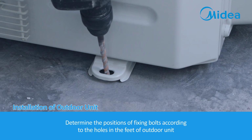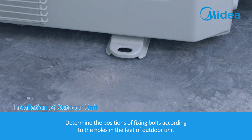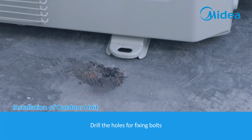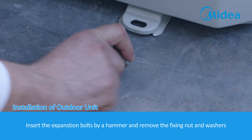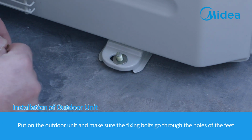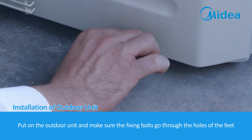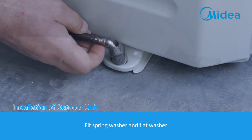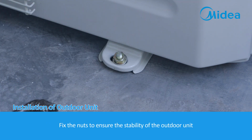Determine the positions of fixing bolts according to the holes in the feet of outdoor unit. Drill the holes for fixing bolts. Insert the expansion bolts by a hammer and remove the fixing nut and washers. Put on the outdoor unit and make sure the fixing bolts go through the holes of the feet. Fit spring washer and flat washer. Fix the nuts to ensure the stability of the outdoor unit.